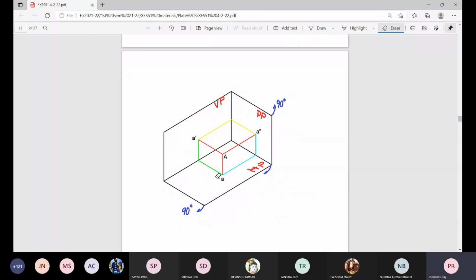Anyway, this is the first quadrant. Am I clear? In the first quadrant, we have placed a point capital A, a particle. We are holding a torch here horizontally, and this is the shadow. Now we hold a torch vertically directly above this particle A. This is the shadow formed here. And this is the shadow formed on the pictorial plane, which is perpendicular to both this VP and HP, just holding a torch from this side. So now do you understand these three shadows?